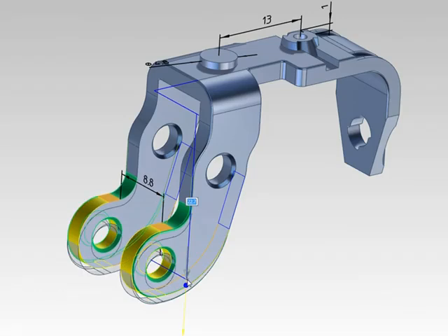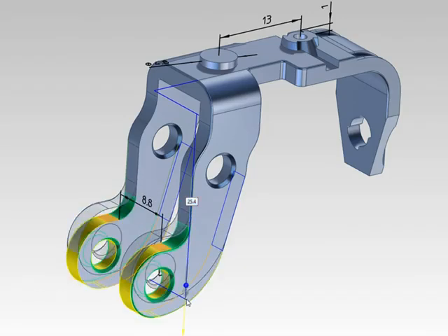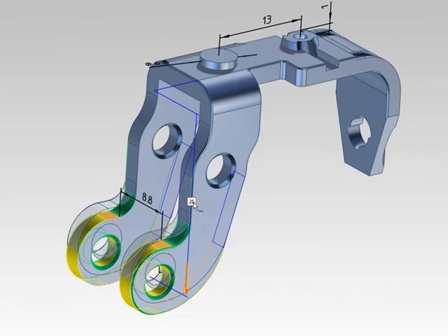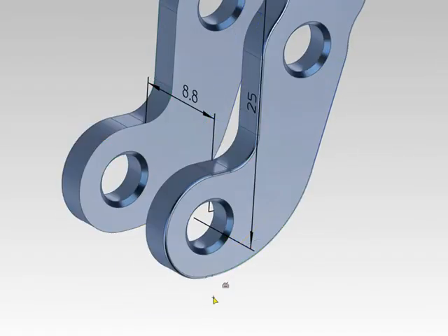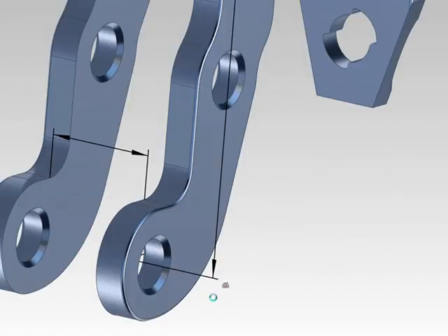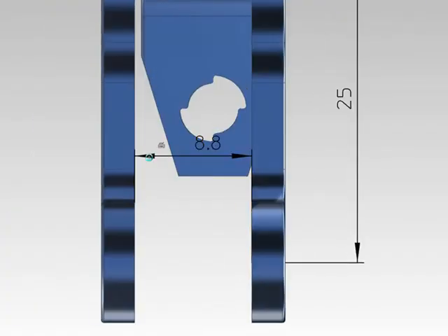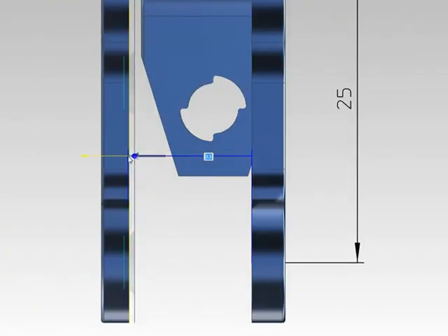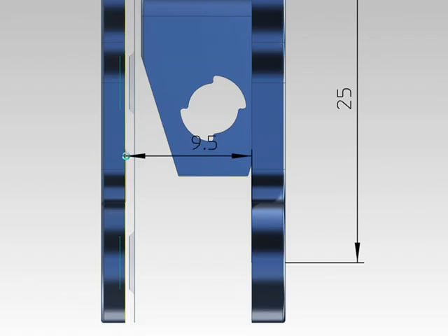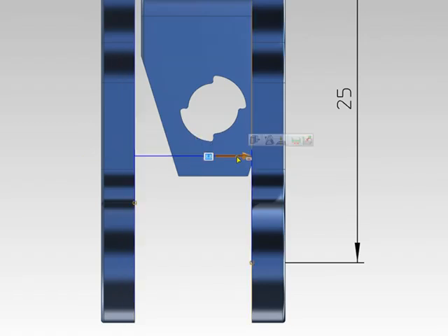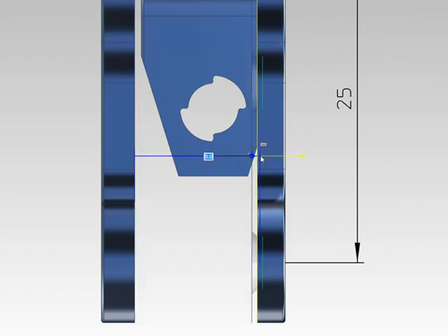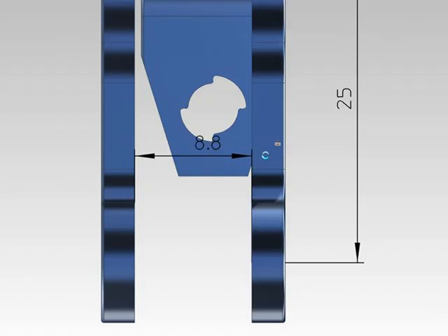See how when I change the height of the design, the tangency conditions are maintained, and the selected through hole and faces are moved in real time in one easy step. If I pick the left-hand side of the dimension, that side moves. If I pick the right-hand side, that side moves. And if I don't pick a side, the change is driven in a symmetrical way.